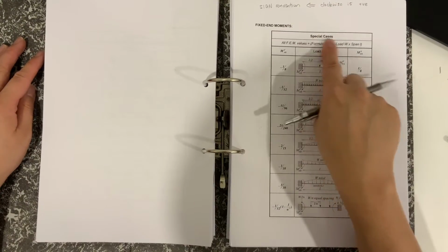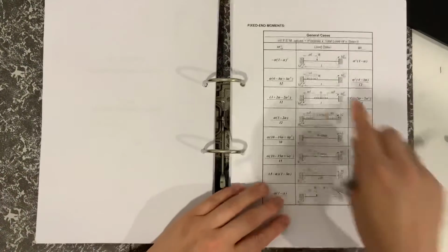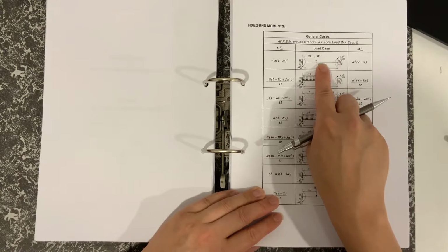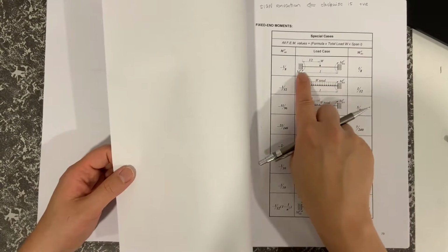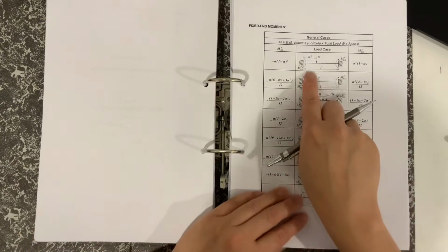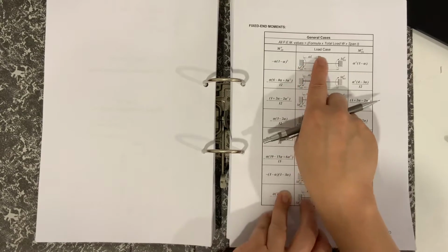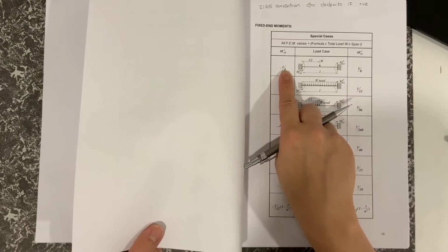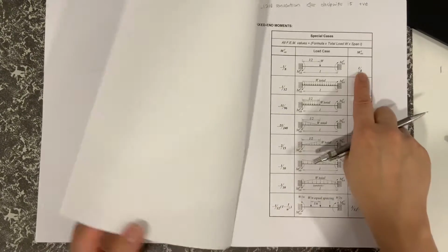So this is called a special case. If we flick through to the previous page, we will see a beam where you can put the point load at any position. It doesn't need to be at the center. But for the specific case of it being in the center, or halfway along the beam, you can get through here by having alpha as a half. So if alpha is a half, then the load is at the center, and you put half in for alpha in these, and you'll end up with negative 1/8. And you put alpha as half on this side here, and you will also end up with 1/8.